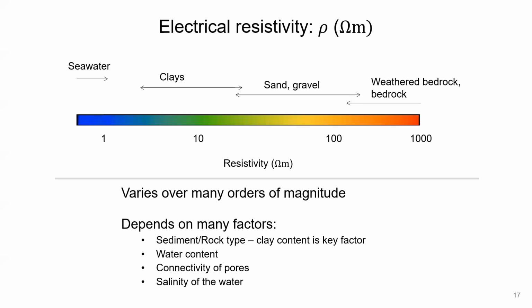So if you actually know the resistivity value, you can infer what the hydrogeology of the system is. Okay? But having a single resistivity value, you're somewhat limited. It's hard to distinguish, for a given resistivity, what was the clay and what was the sand and gravel. So that's the general limitation or challenge that we're up against when using this electromagnetic imaging for characterizing the subsurface system.